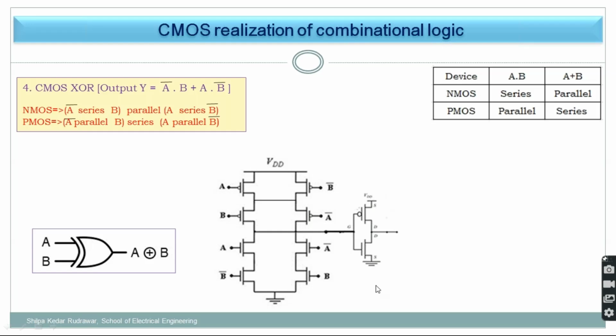Now, why have we connected this CMOS inverter in front of this? Because I already told you CMOS logic implements inverted logic, and as we know over here, what is happening? There is no complement present. So that's why I need to implement this logic. Whatever CMOS is implementing, it is implementing complemented logic. To remove that complement, because I don't have a complement, I need to connect this CMOS inverter.